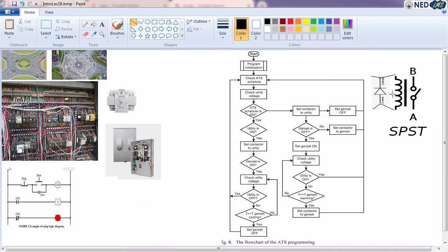Okay, so we have a diode connected in reverse actually. So the 5-volt supply coming in here is going to energize the relay. Once you disconnect the 5-volt supply, it's a DC relay actually, the electromagnetic field will collapse and it will introduce a back EMF. If you do not have this diode in here, that back EMF will have disastrous consequences for your control circuit. It might burn off your microcontroller board here.